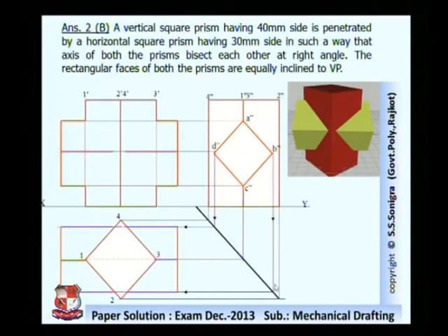Now we have to find the points of intersection and this curve, this line of intersection. You can see this line here. So how to find that line of intersection? For that you pick up this point. This point is visible in top view somewhere here. In top view, the intersection of this square and this edge is this point, and from that point draw a straight vertical line that will cut B dash and D dash in front view at this point, like this.